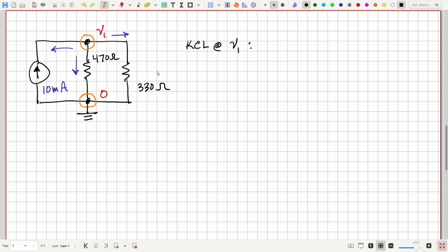It would be, let's call this, say, IA, IB, and IC. Okay, so KCL would be IA plus IB plus IC is equal to 0 because we put these referenced positive all flowing out. The sum of all currents flowing out through a closed surface is equal to 0. So now the key is to put in, using Ohm's law or other relationships, what these currents are and get an equation in terms of the unknown node voltages.